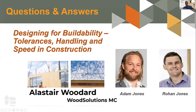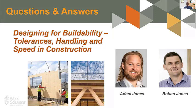Thanks for that, Rohan. All right, well, we've certainly got time for some questions and answers. We've had a number of questions come up today. Might just start off with one for you, Adam, from Lisa. She was asking about the different EMCs and moisture transfer in a panel, especially if there's been some construction wetting and the EMC might have gone up to around 15% or more. What do you recommend to avoid stress concentrations from drying stresses when this panel starts to dry back down? Is there anything you can do there?